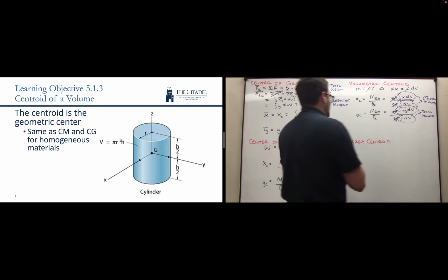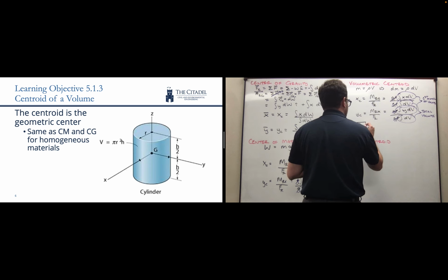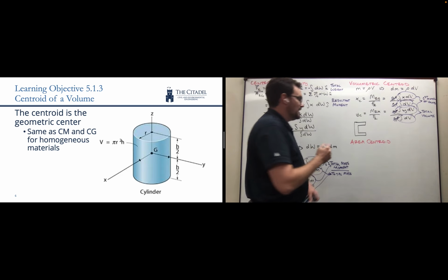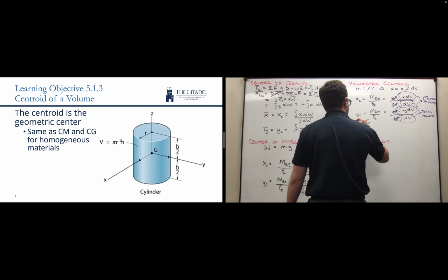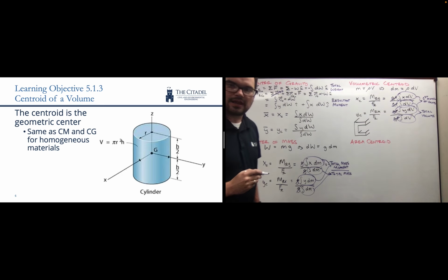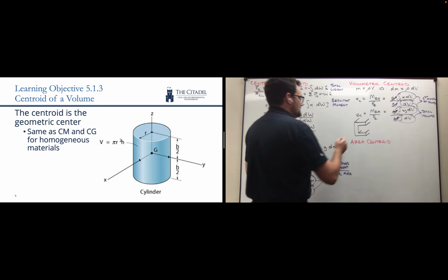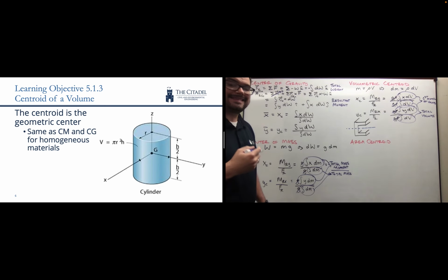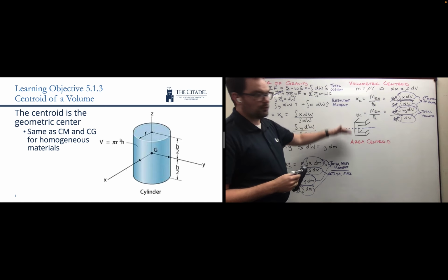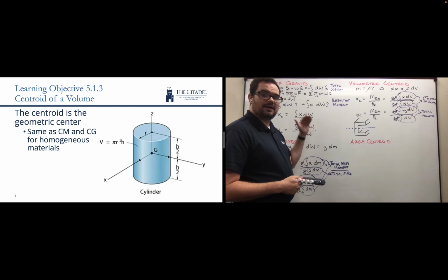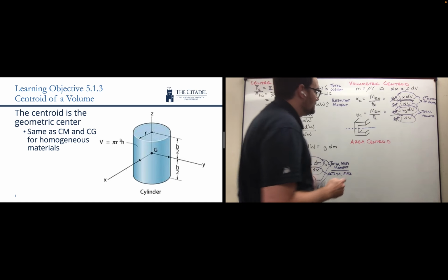So for example, if I have a channel shape that is symmetric around a particular axis, so something like this, say this is a 3D extrusion of a channel. I'll attempt my crude 3D drawing. There's a nice little 3D drawing. Y'all like that? We notice that that looks like an axis of symmetry, and therefore that axis of symmetry is the y location of the centroid. So sometimes we can actually calculate the centroid of a shape just using inspection.